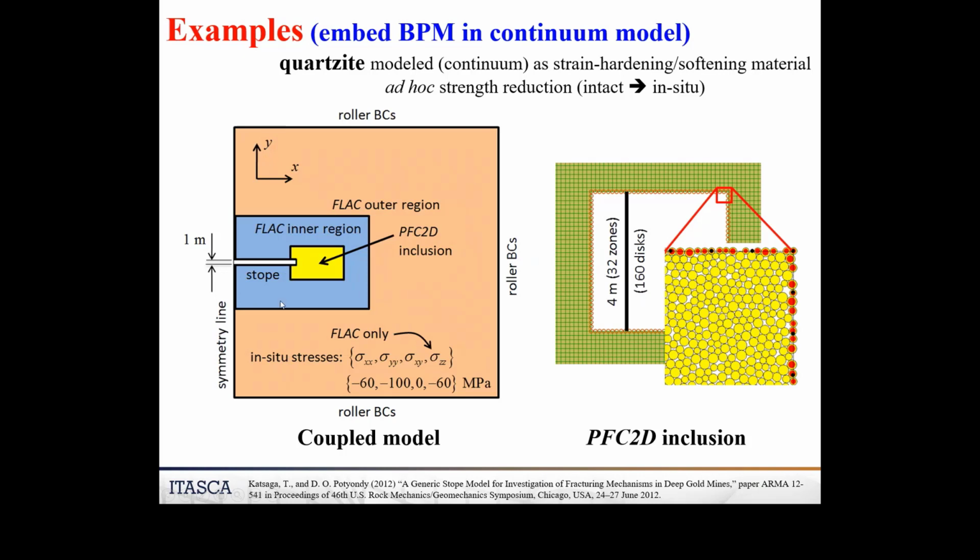And what they do is they go to this face and they keep blasting this face all along the whole distance and keep moving this forward. And this is in a very, very high stress regime. The in situ stresses are on the order of 100 megapascals because it's deep underground. It's a very hard rock.